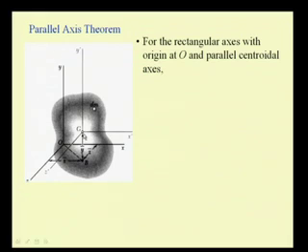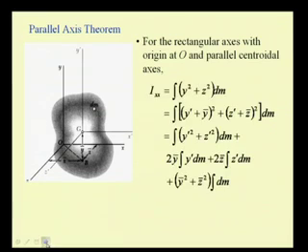This point G is located at x bar, y bar, z bar, which are the coordinates of this centroid with respect to our original axis O, x, y, z. Now, let us write the equations for computing the second moment with respect to the x axis, Ixx. As per our discussion earlier, this is equal to the integral of y square plus z square dm.